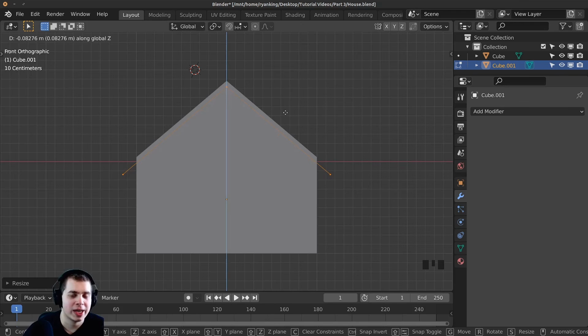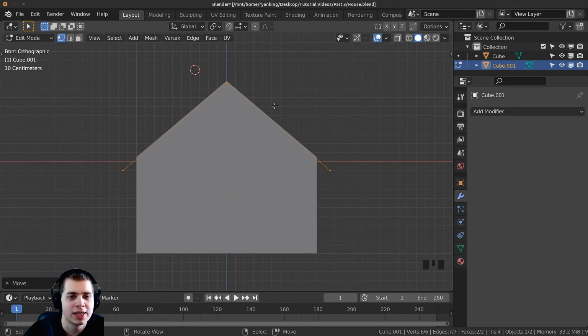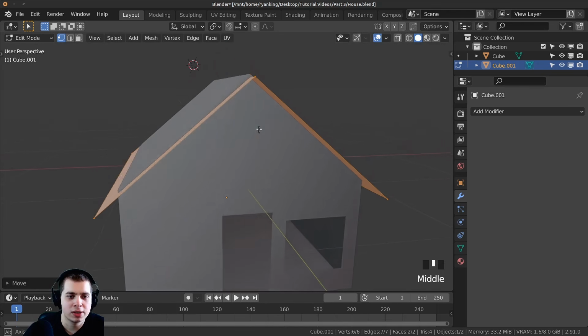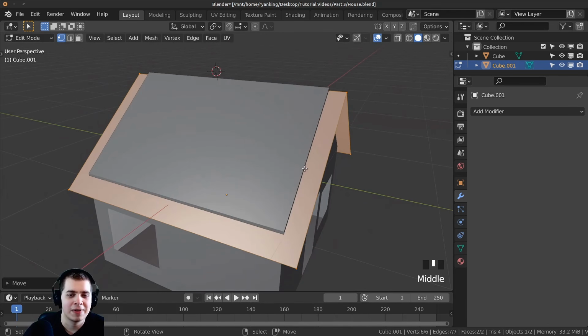And then whenever you're doing an action in Blender, like moving this, if you want the movement to be a lot more sensitive, while you're moving this, you can hold down the Shift key. And you can see when I'm moving this, I'm not holding down the Shift key. Now I hold down the Shift key, and you can see that the movement is a lot more sensitive. So I have to move my mouse a lot more. And this is super useful if you're trying to get something really close. So I'll just click now and place that. And now if I click and move out, you can see there is our roof. Now the top of the house is coming through the roof, so I want to give that roof a little bit of thickness.